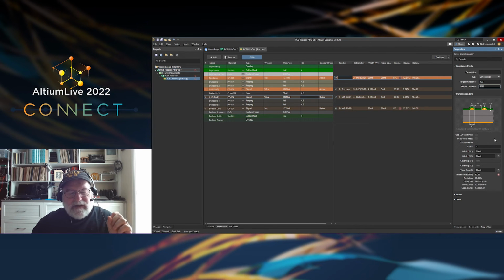And so I always recommend following rule number 9, which is before you do that simulation, you do a quick estimate of what you expect to see. So we're here at 20 mils wide line, 20 mil spacing between them, and that's 87 ohms. I want 100 ohms. I want a higher impedance. And if I keep the spacing fixed, that means I have to make the line width narrower. So I'm going to expect to see a narrower line width for W2, the top dimension. Let's see what we get. We push that.